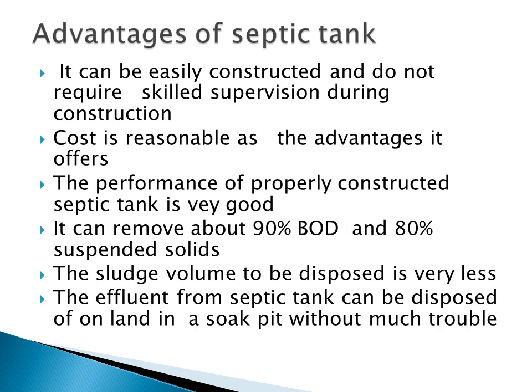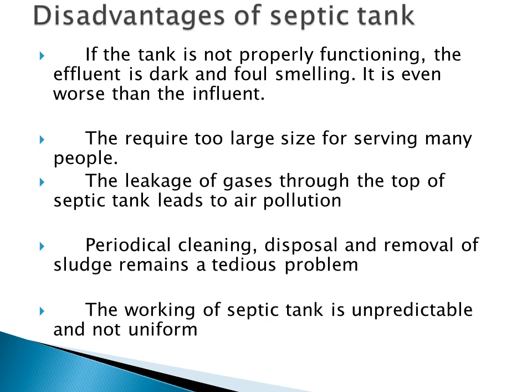Now the advantages of the septic tank are: it can be easily constructed, no skilled supervision is required, and the cost is reasonable compared to the Imhoff tank, which is an improvisation of the septic tank. The performance is also almost good, it can remove about 90% of BOD and 80% of suspended solids, and the sludge volume to be disposed is very small. The effluent from the septic tank we can dispose onto land in a soak pit without much trouble. Those are the advantages.